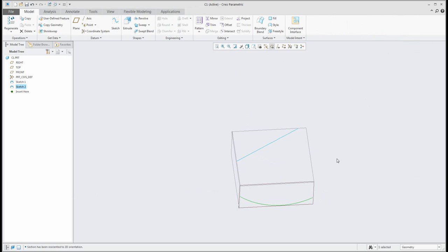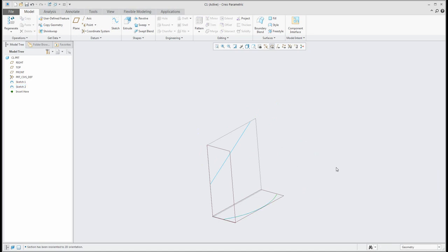So what does the system do? If you imagine that sometimes you need to create an intersection between two curves, you can select the first curve, Control, second curve, and then in the ribbon you can select the function Intersect, and the system will create for you a 3D curve. Yeah, so you can see here right now I have my 3D curve.